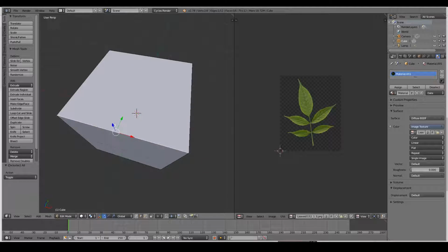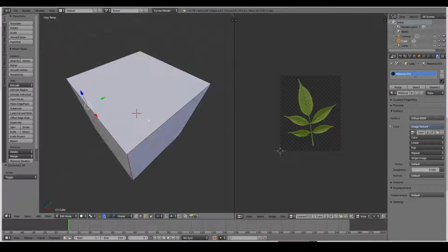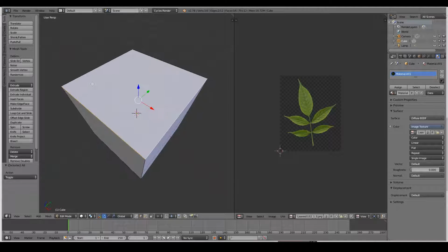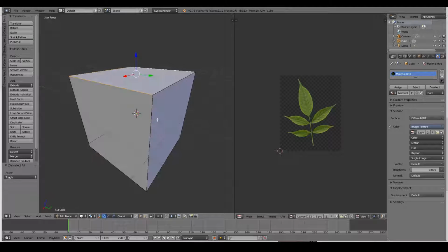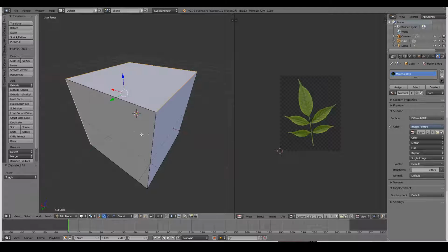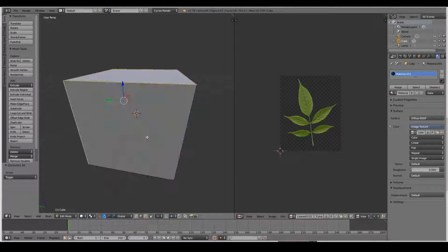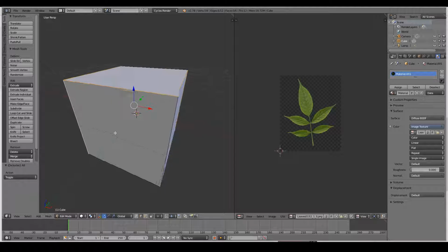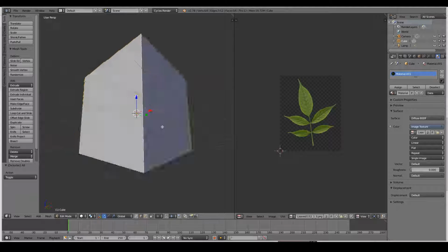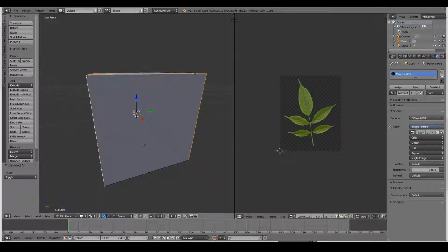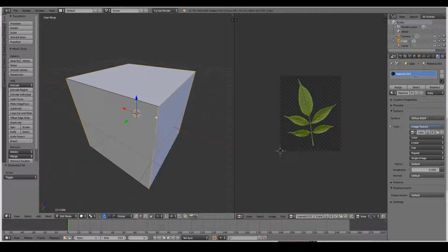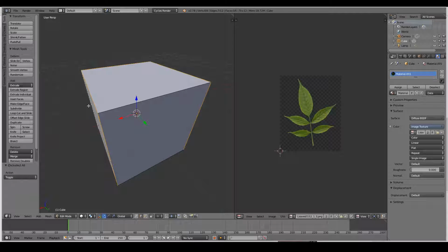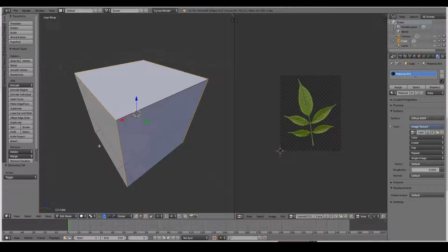And let's select that one. That one. That one. But I don't want to cut this. I want to keep this joined with this one. But I don't mind cutting this. This. This. And this. I think that should be good. So that should tell Blender's scissors to cut along these edges without having to create separate pieces for each face.